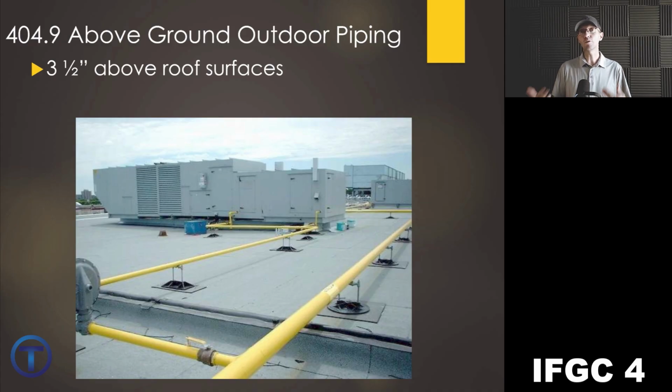But if you do that, then you also have to keep that gas pipe elevated above the rooftop, and the code says that has to be at least 3.5 inches above the roof surface. There's a variety of ways you can do that. This installation included roller mounts where the expansion and contraction of that pipe can happen, and it's just going to stay supported whatever happens out there. But that's the rule, 3.5 inches above the roof surface.